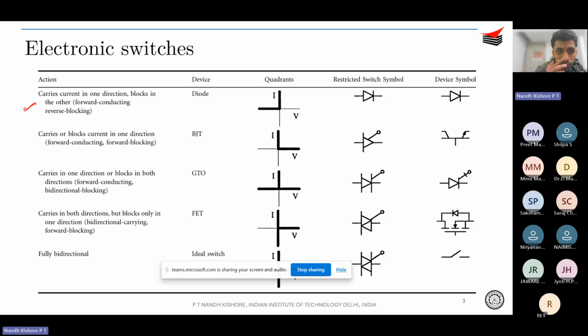That is diode. You of course know that a diode is an uncontrolled device, in the sense that it is able to block negative voltage, that is from cathode to anode, and it can conduct current only from anode to cathode, right? So it's a unidirectional device and blocks in the opposite direction, and it is of course uncontrolled. If you want control, you of course need to go towards BJTs, GTOs, FETs, SCRs, DIAC, TRIAC and stuff, right?